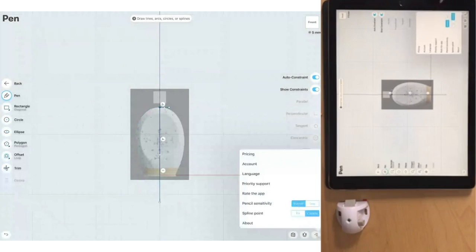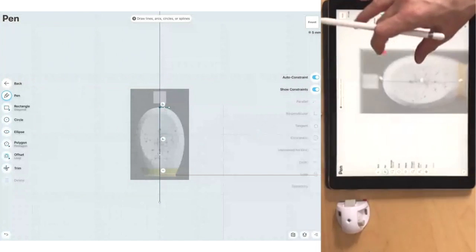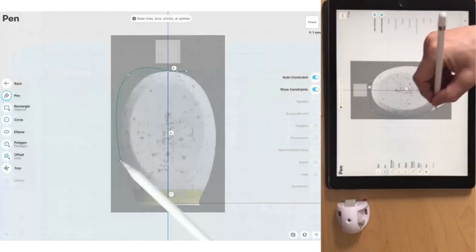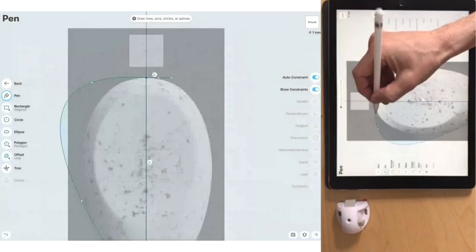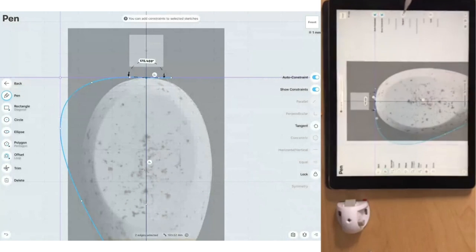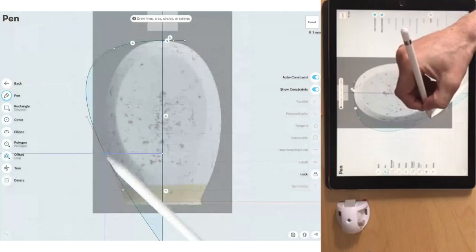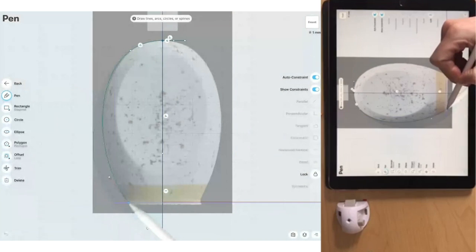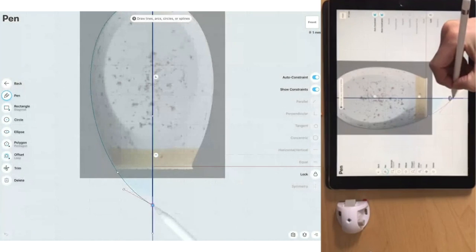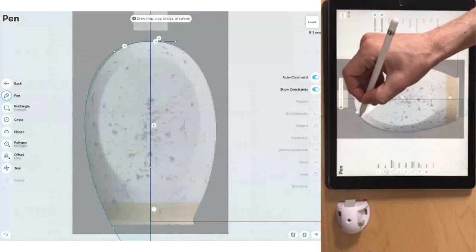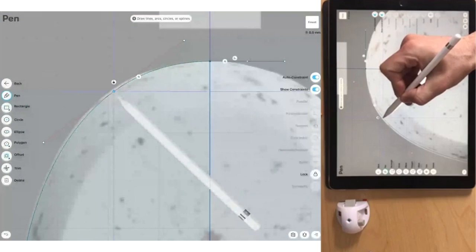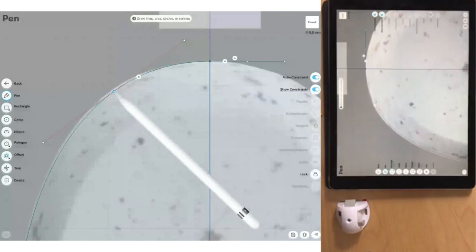With the fit point, which gives in general smoother results, but they're sometimes a little bit more tricky to work. Think about the fit point as kind of like stiff plastic. You can bend and it always has really nice deformations, but it has its mind on its own. So when I move this point, you see how this area, for example, deforms a little bit. And then I can move this point, straighten this out, move this to there. There's really no one is better than the other. It really, I think, can come down to which do you like to work the most with.